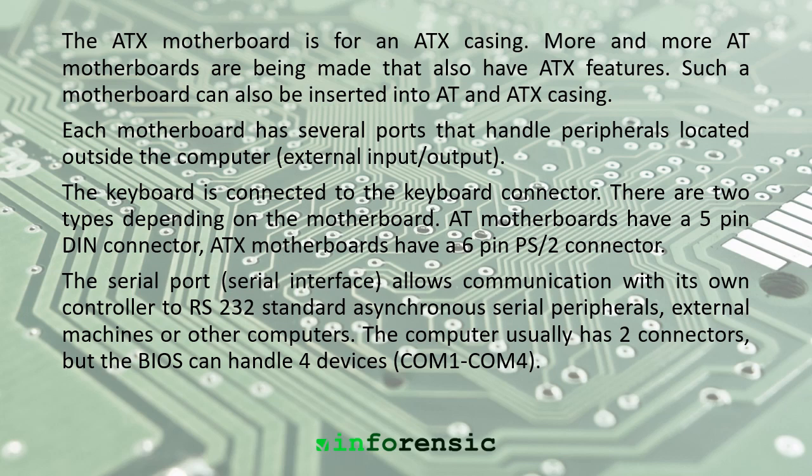Each motherboard has several ports that handle peripherals located outside the computer, external input-output. The keyboard is connected to the keyboard connector. There are 2 types depending on the motherboard. AT motherboards have a 5-pin DIN connector, ATX motherboards have a 6-pin PS2 connector. The serial port, serial interface, allows communication with its own controller to RS-232 standard asynchronous serial peripherals, external machines or other computers. The computer usually has 2 connectors, but the BIOS can handle 4 devices, COM1 to COM4.